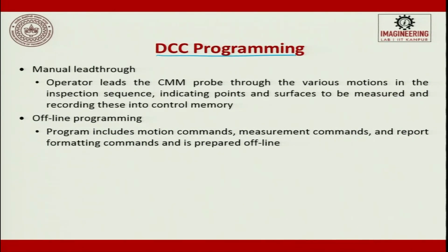So, DCC programming. Again, you can have 2: manual lead through. The operator leads the CMM program through various motions in the inspection sequence, indicating points and surfaces to be measured and recording this into a control memory. So, the same thing that we had in robotics, we also have here, manual lead through. The second one is offline programming. The program includes motion control, measurement commands and report formatting commands, which is done offline from the data which is getting generated, or you generate a program and then you push it inside between the free time or during the